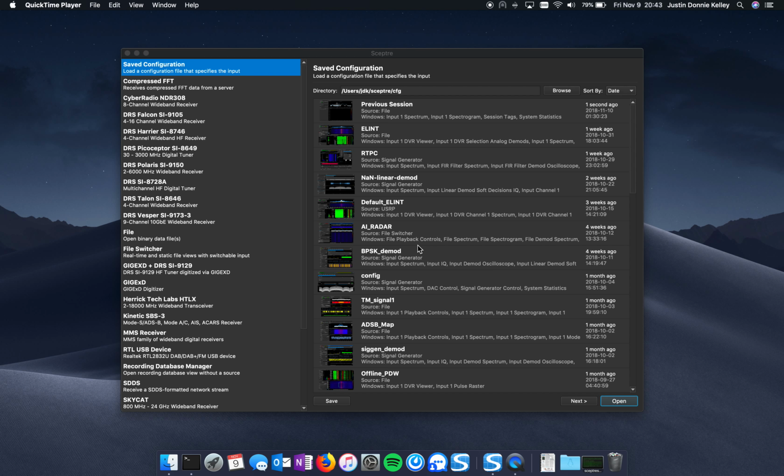The versatile nature of Sceptre allows a user to leave it unattended for theoretically days. There's a circular FIFO buffer inside of Sceptre that, should you have the storage capacity to support it, you could just let it run indefinitely until that storage buffer fills up and then begins to roll off. Then you can go back in time, place a tuner, do an extraction of raw pre-D of the area that you're interested in, save it off and recall for analysis later.